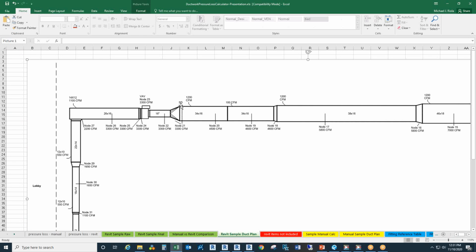So in this case, where something is separating this Y from the transition, it is not a tight arrangement. There's a little bit of space right here, whereas right here you take off and then you transition pretty much immediately. In this situation, you have a smoke damper right after the takeoff. So you would still have your diverging Y main coming through here, but the duct size is going to be the same on the outlet of that Y as the inlet. Then you're going to have your smoke damper, and then the transition in this type of situation.